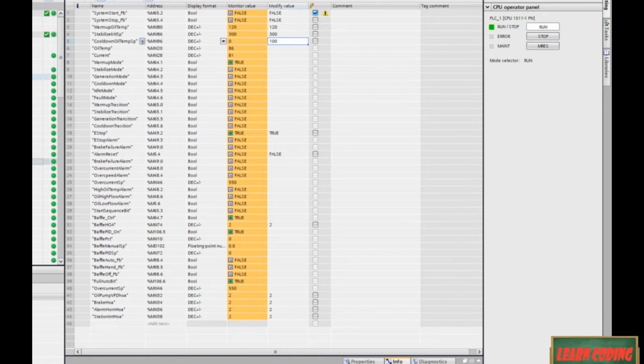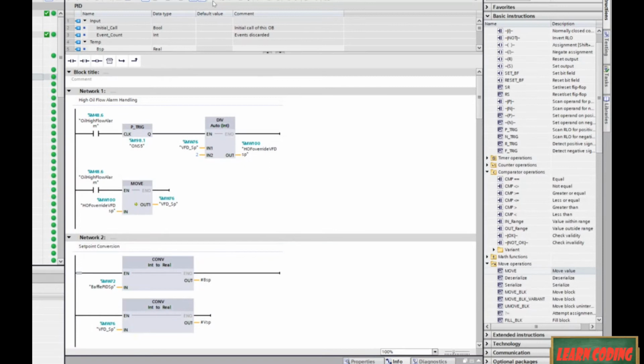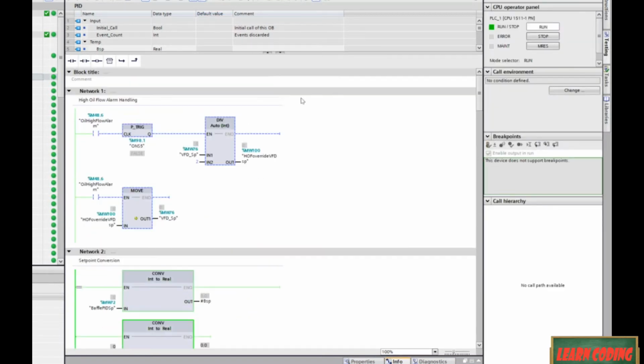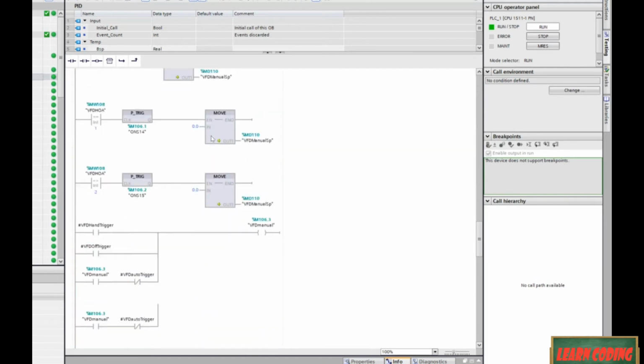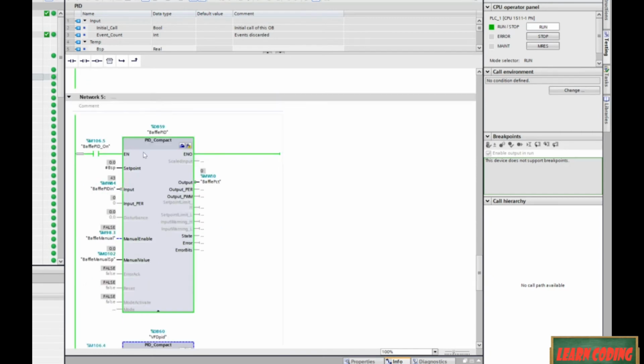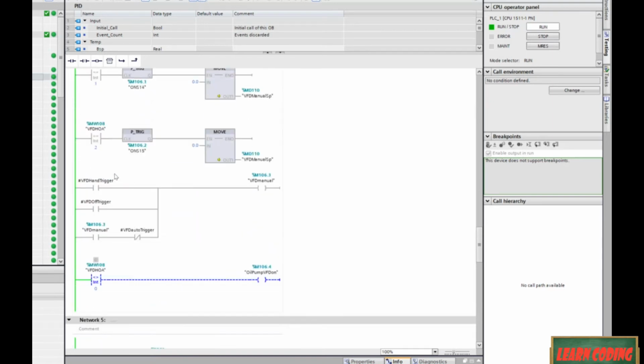Let's jump into our PID here, and let's just take a look and see what's going on. So I'm going to put this in to monitoring, and let's come down to our actual PID and see what we're sending in. We're sending in a set point of 0. That's a problem. We are not in manual mode. We have a manual value of 0, so we're not worried about that. Our input coming in is 64, but our BSP should be whatever our warm-up oil temp is.